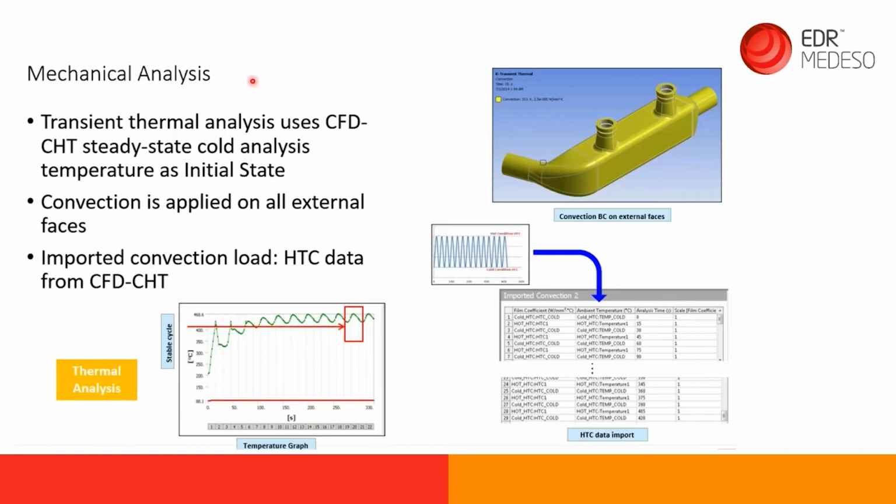So in the mechanical analysis, we've brought in a CFD CHT steady state cold flow analysis. Then we can apply convection conditions on the mechanical model, and then we can run a cyclic thermal analysis mimicking how that component would behave as it's being used. You can imagine it's subject to highs and lows all of the time. So CFD gives us that coefficient, and Mechanical takes it forward and does a transient stress analysis on it.